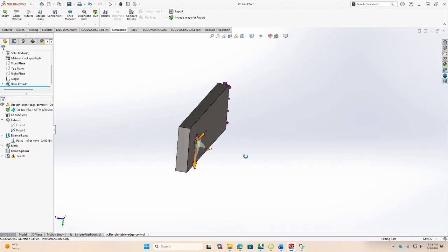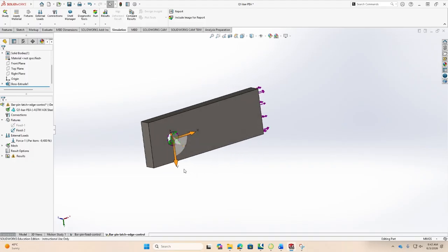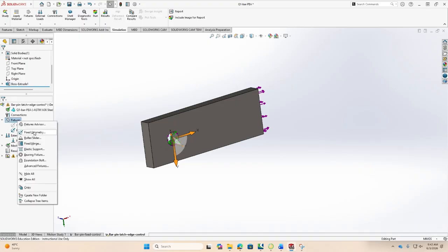Now in reality the bolts will always be through some washers, so there will be a slightly bigger area. So the actual stresses will hopefully be slightly smaller. But what I'm trying to mimic is the extreme case situation.